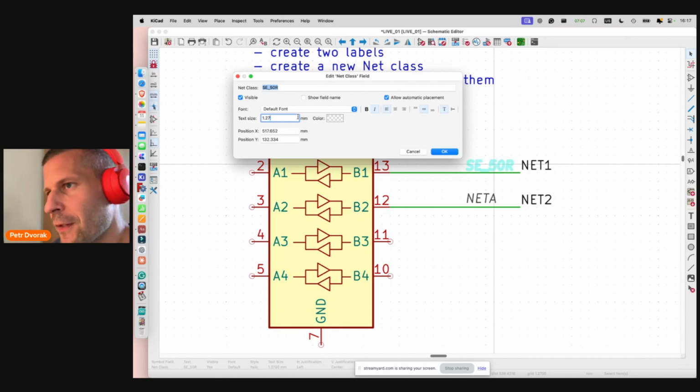Instead of dividing 1.27 in half, you just hit /2 and see KiCad do the math for you, which gives 0.635. You can choose any other denominator, but be careful: when you leave the window, the formula will be lost and only the value will stay. So now I set half of the default value.